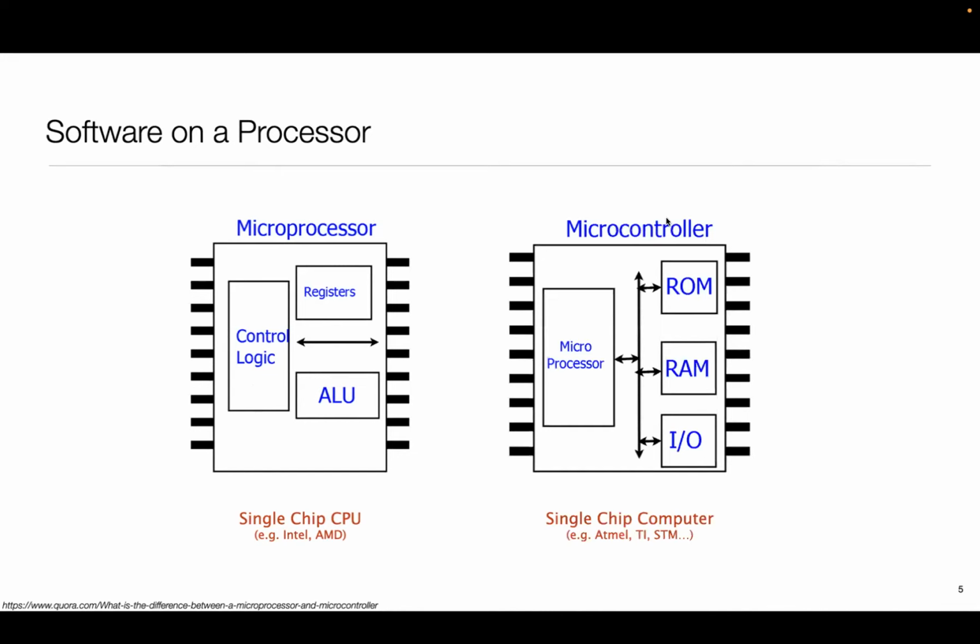Next up in integration is what are called microcontrollers. So microcontrollers take the microprocessor, but then put them with ROM, RAM, IO. So the program is here, RAM is here, a bunch of IO stuff is here. What Apple M1 and some other, I think some AMD processors and Intel processors probably have the same way, they basically combine this part, RAM plus microprocessor, into the same package.